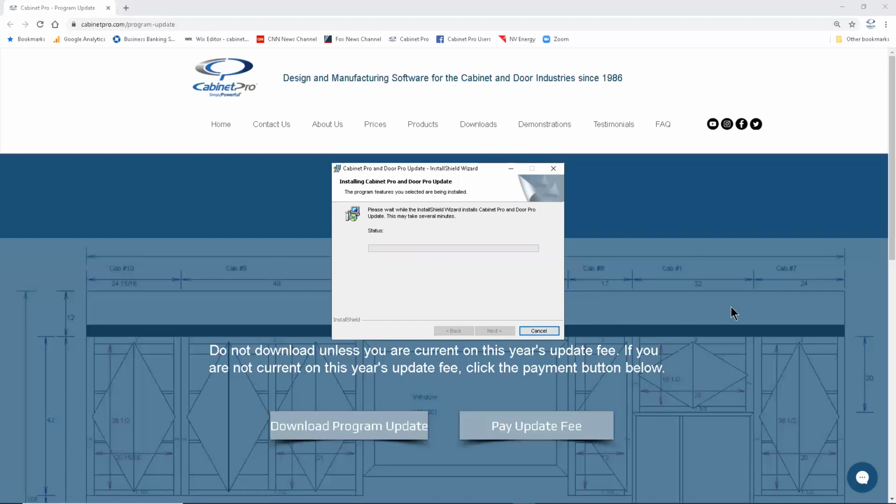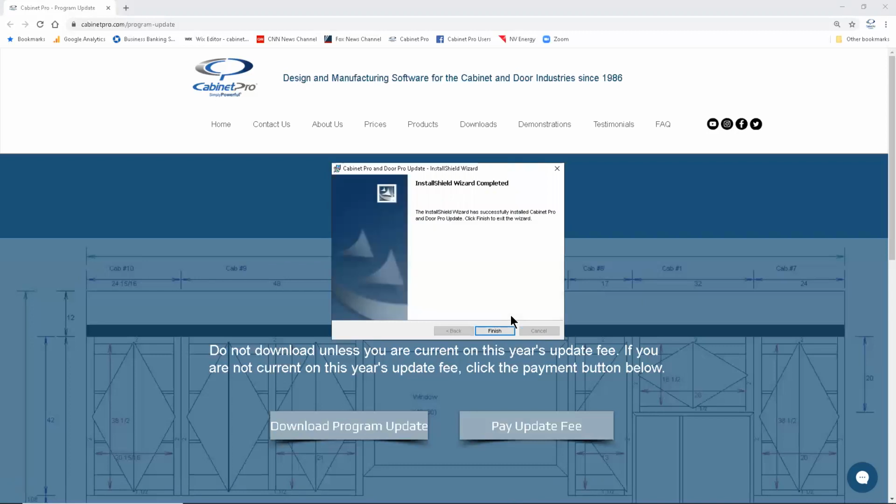That's been changed drastically, and you don't have to change this on your router, but you may indeed want to, because when you install this update, if you haven't changed it, if it's anything less than 20 degrees or greater than 80 degrees, the program will automatically make it 45 degrees. So we've changed it from an actual distance to an angle.